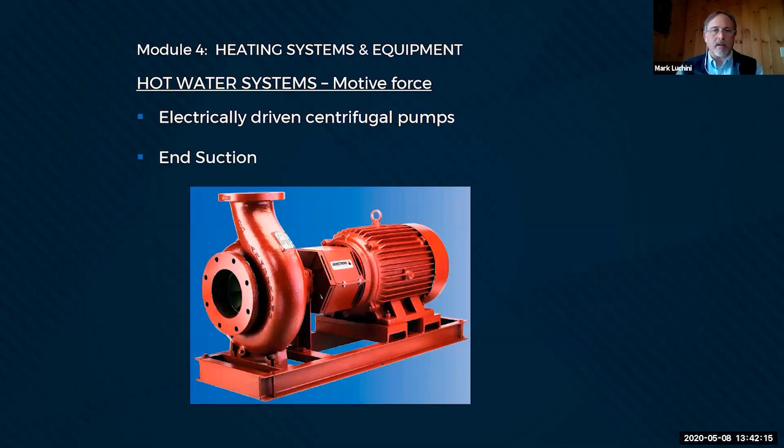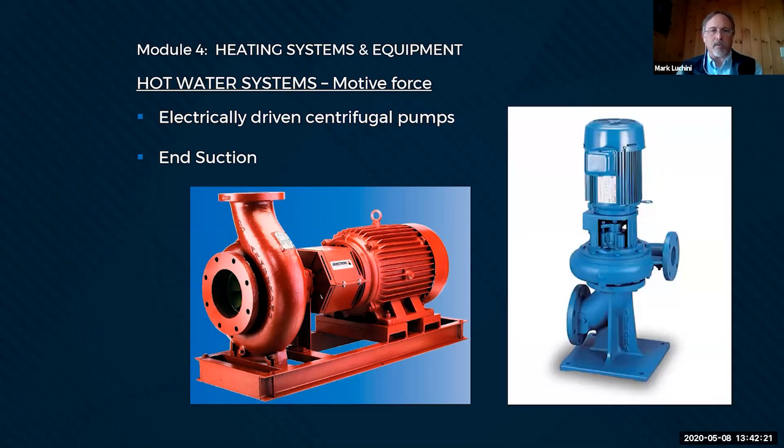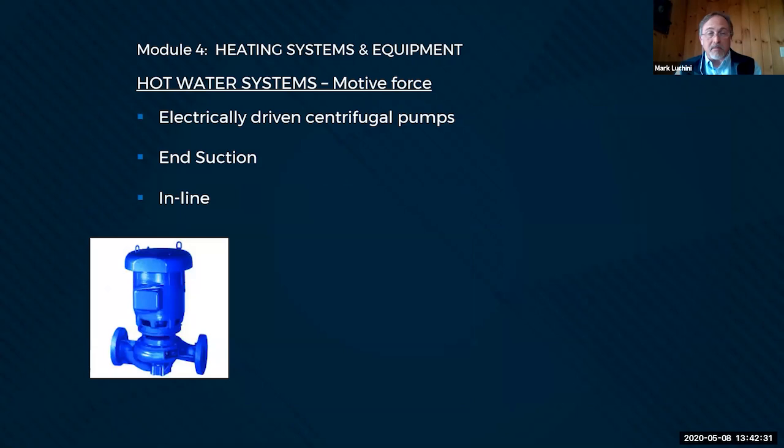Okay. Somebody said, well, that takes too much room. I only have half that footprint. Okay, well, we'll weld an elbow on the inlet and give you a stand, and now it's a vertical end suction pump. Why they would do that rather than just install an inline pump, I really don't know. I'm guessing that the equivalent inline pump to that vertical end suction is probably about two-thirds the cost, but that's a guess.